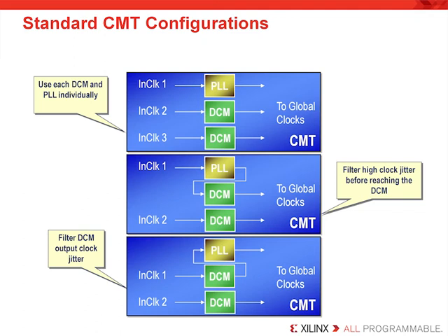And in the bottom example, the PLL can take a single DCM output clock and create an ultra-low jitter version for global clock distribution. This is commonly done when a designer is using the clock FX output of the DCM. It is expected that the second option will be especially useful. In this case, the PLL can accept a much wider range of input frequencies, duty cycles, and input clock jitter than the DCM. Using the dividers, jitter filtering, and duty cycle correction in the PLL allows the resulting clock to be fed to the DCM, which can then perform its further clock functions.